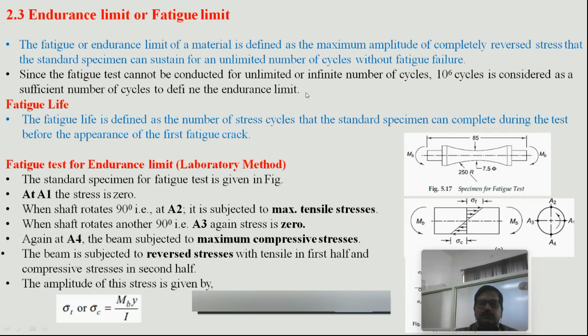This endurance limit is very important for the design of machine elements or components which are subjected to variable stresses. The one which is having more than 10 power 6 cycles of life can be treated as infinite life, and less than 10 power 6 is finite life.